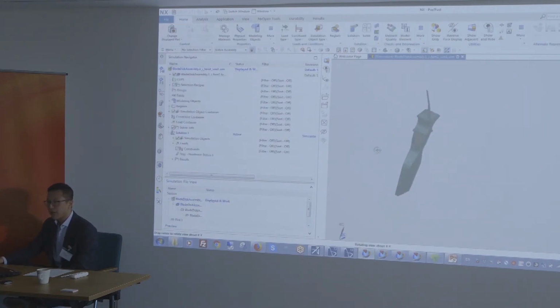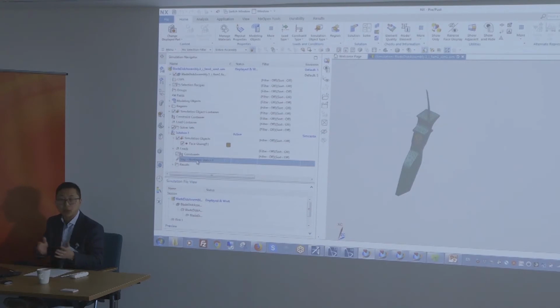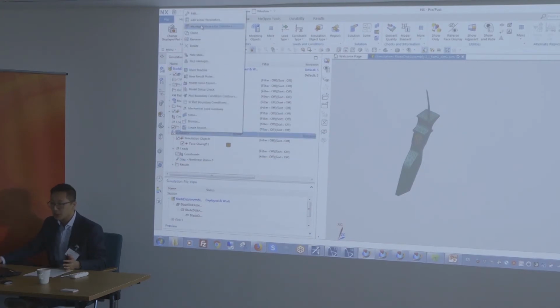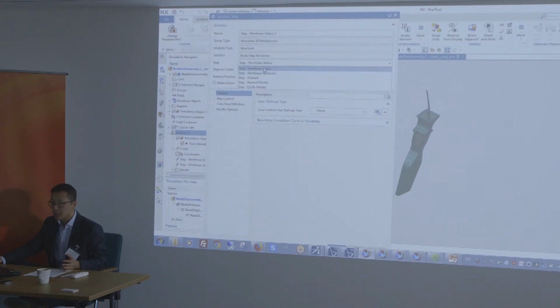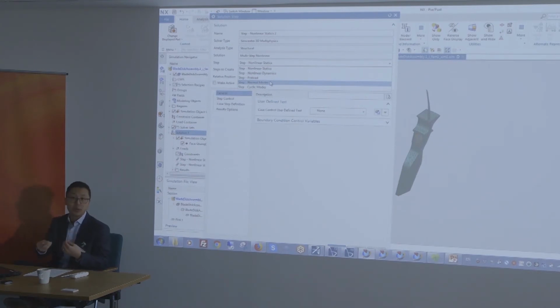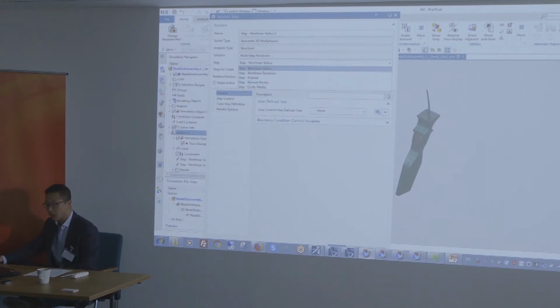Okay, I've heard mission cycles or condition sequences earlier, I think from you. We do have those kinds of features. So in terms of substeps, we can define multiple cases. We can define a case for nonlinear static that varies from 0 to 100 seconds, then apply a thermal load. In this case, here, if I look at the different steps, I can create static, I can do dynamic loads within the same environment, one after the other. I can run normal modes, get the natural frequencies, load it mechanically and thermally, and then recalculate the frequencies to see what changed from hot to cold. Right? Do I have a different behavior? So all of this you can accomplish.